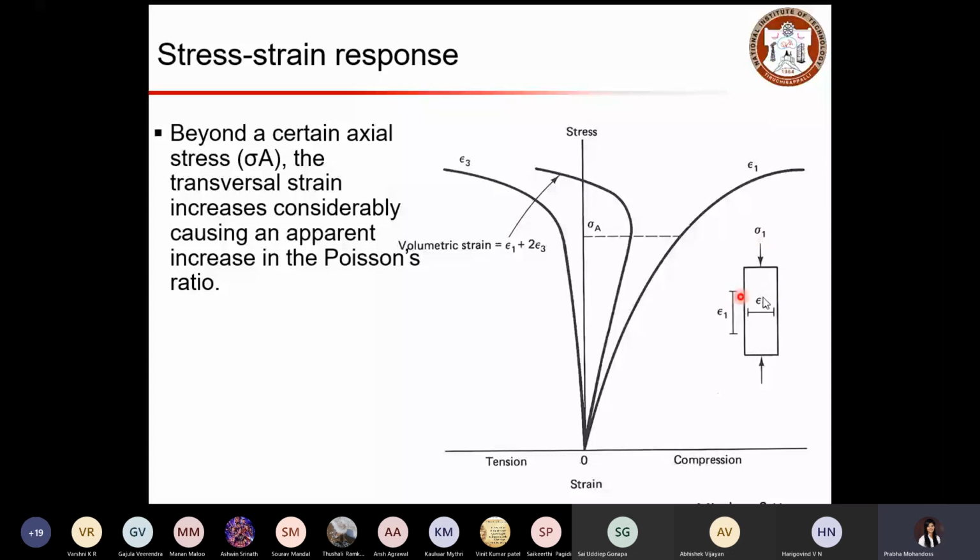When this material deforms significantly, you will start seeing a reduction in the volume. In that case, this central portion represents the volumetric strain. The relationship for volumetric strain is that it is one times the axial strain minus 2 times your lateral strain. So you can see your volumetric strain will also increase with loading, but beyond a point, your material will fail and will collapse and deform.